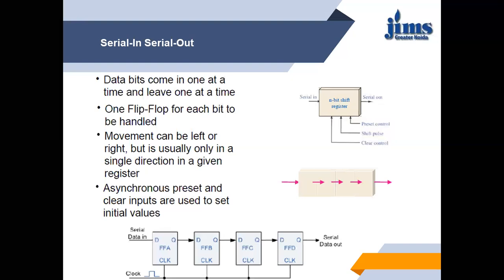So it will be convenient, when we have to design a register, to use D flip-flops every time. When I was discussing flip-flops, I told you that it is a data flip-flop, meaning whatever the data is, whenever clock is active, the data will be at the output of the flip-flop. That means it simply stores the data. So it is convenient to design a shift register with the help of D flip-flops.